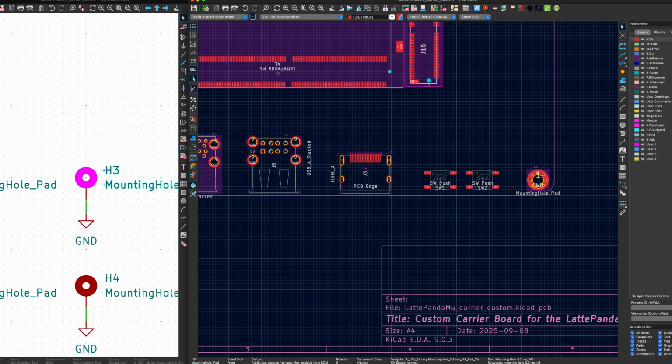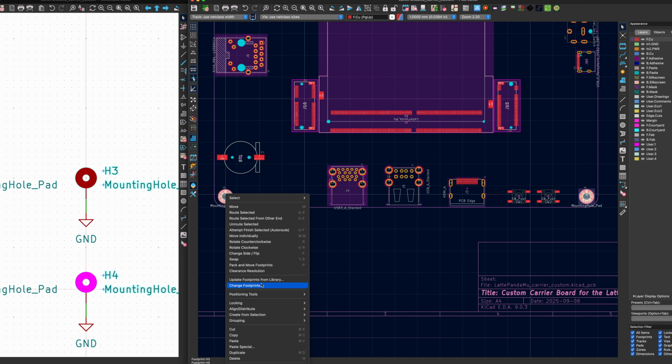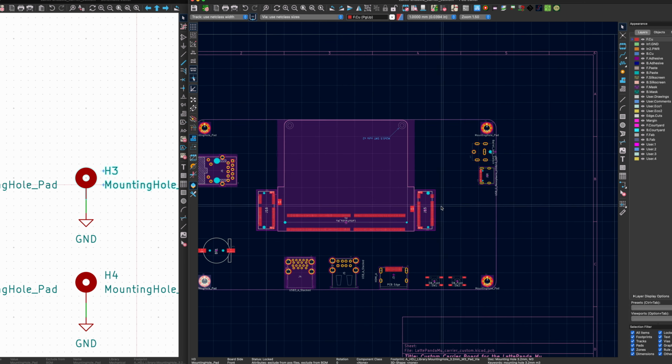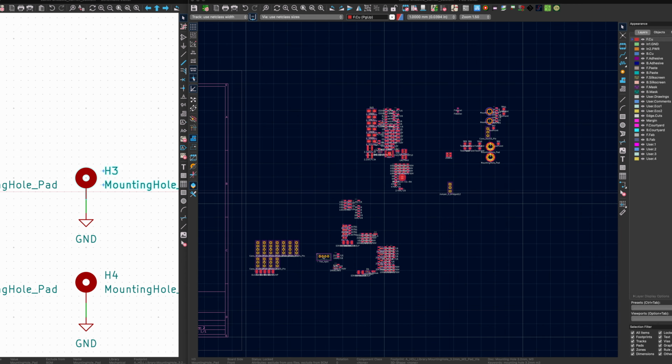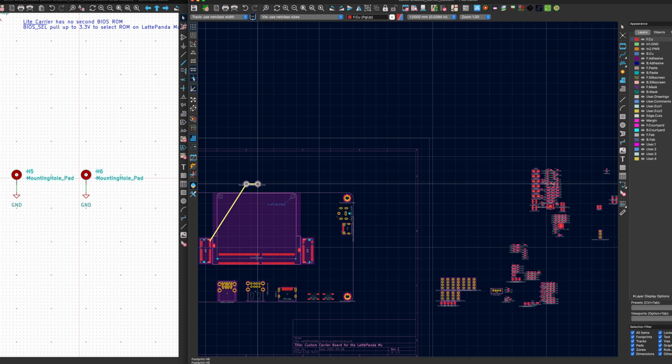Finally, you'll see how to prepare your design for fabrication and assembly. You learn how to perform ERC and DRC in KiCad, how to review footprint accuracy and component orientation, and how to export clean manufacturing files, including Gerbers, drill files, and fabrication notes.